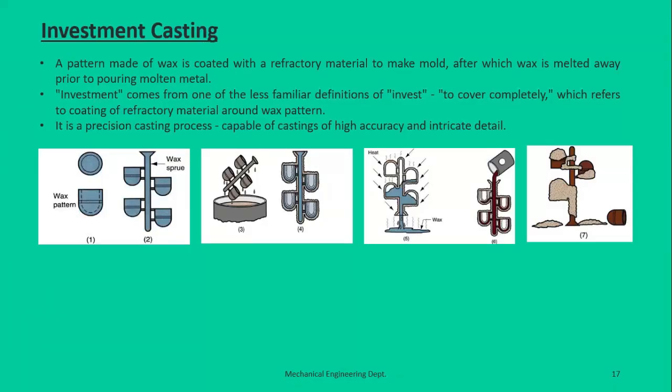Another type of expandable mold casting is investment casting. The word invest means to cover completely, and again it refers not to the final product but to the mold cavity itself, like in the case of vacuum molding. In investment casting, we usually make two patterns.